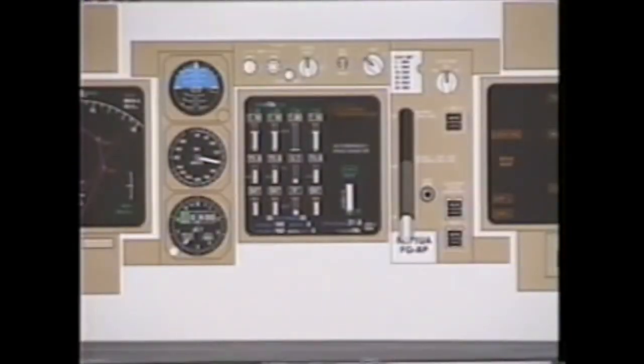Continuing a review of the center portion of the forward panel: our standby instruments, standby altimeter, standby airspeed indicator, and standby attitude. Brightness controls for the upper and lower ICAS. EIU selector, 3 EIUs. This EIU in the auto position allows the left EIU to generate the primary and secondary graphics on the primary and secondary ICAS. You have the ability to select any of the 3. Likewise, with this in auto, if the left EIU was to fail, the center EIU would pick up the primary and secondary ICAS. Heading select switch, whether it be true or magnetic heading.